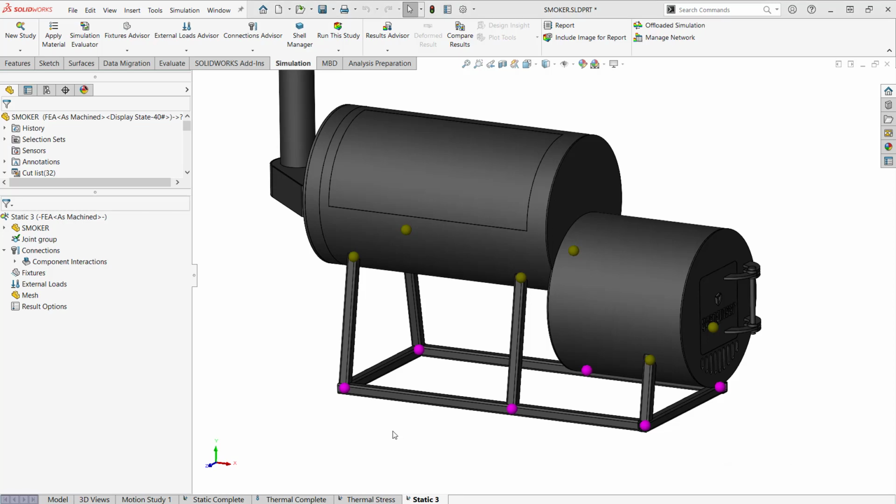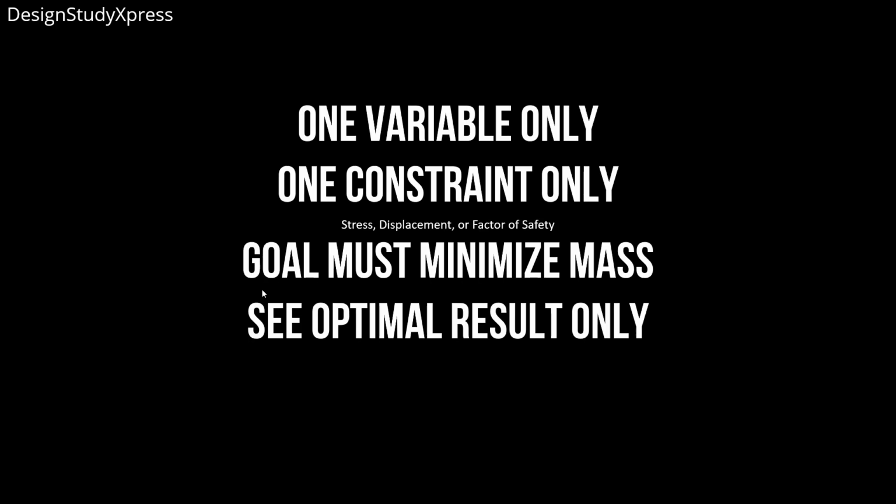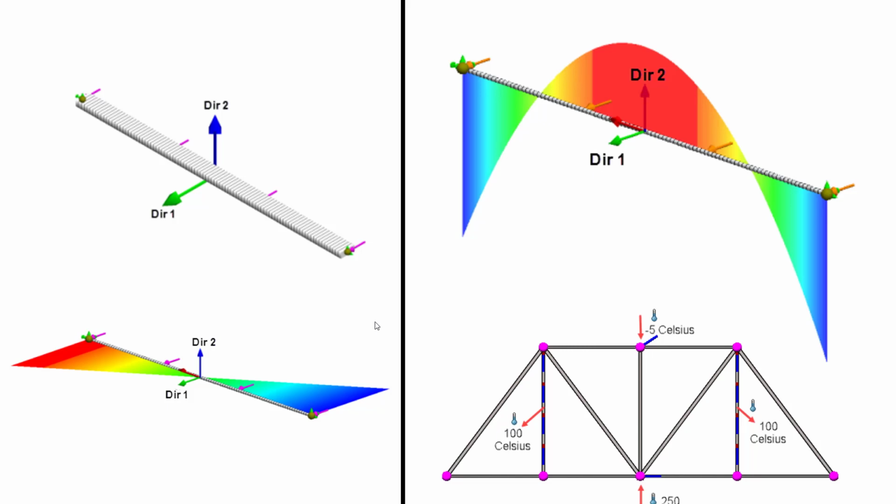I've got an example. Oh, not in that PowerPoint, but this PowerPoint. So a beam element takes a structural member and simplifies it into its moment of inertia and a cross-sectional shape, the length, things like that. And out of it, you can get things like your shear diagrams and your moment diagrams, as well as things like stress and displacement. It's really good for assemblies that are just made out of beams, like bridges or skids.